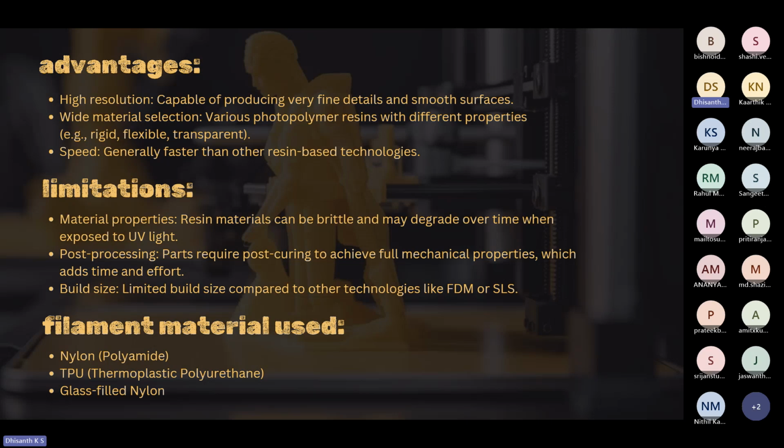The limitation is the material properties. Resin materials can be brittle and may degrade over time when exposed to UV light. As seen before, the resin is cured by UV light. So with exposure to UV light and sunlight, it may get brittle over a long period of time.